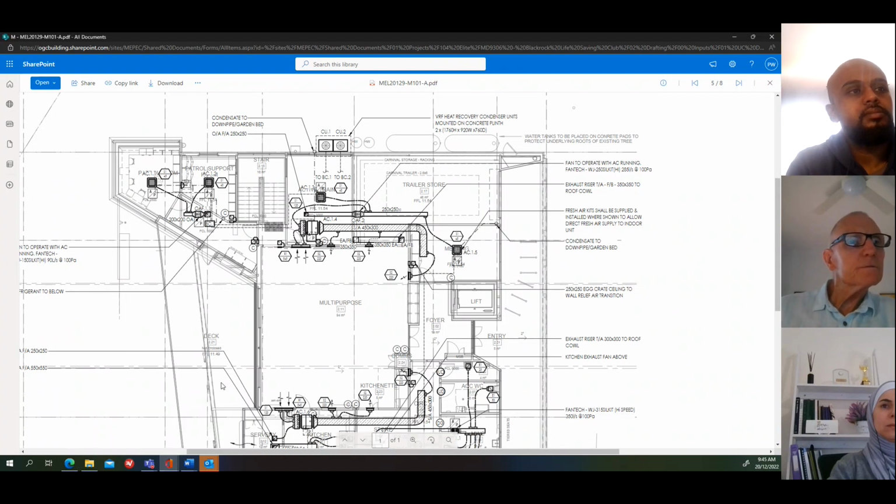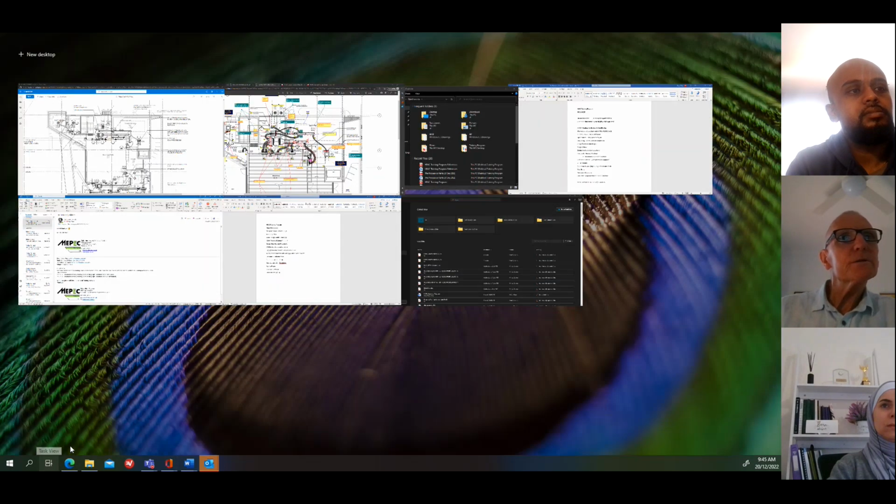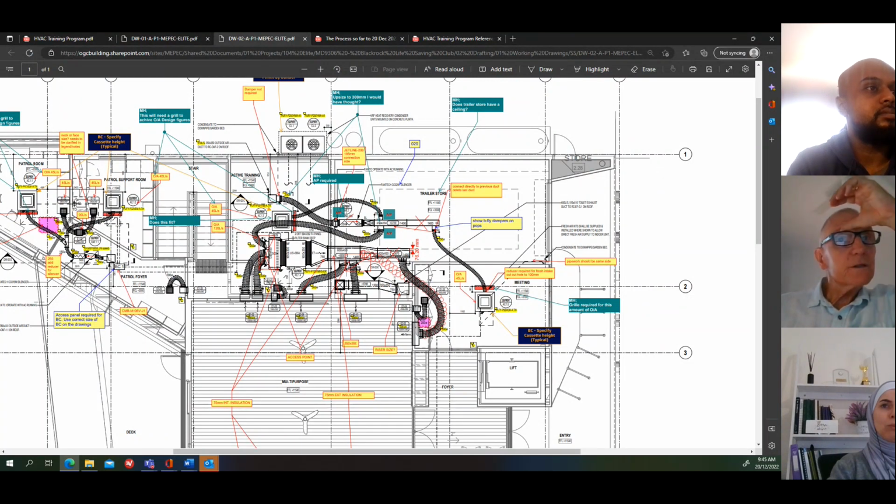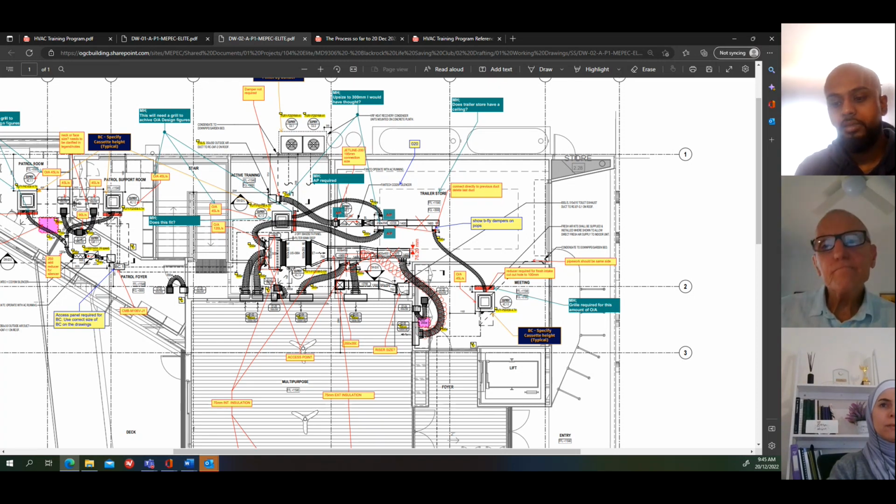If we come back to the other drawing, this one. This is the workshop drawing that's been developed from that design drawing. So you can see now, this piece of duct, for instance, it's 600 by 450. Now, do you guys know what that means? What do those dimensions refer to on a workshop drawing? Sheet metal. Sheet metal size. And the insulation is where?